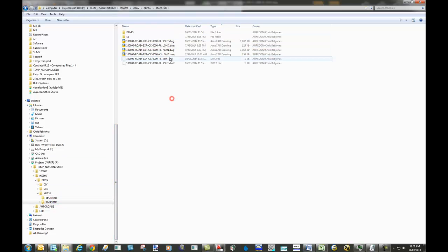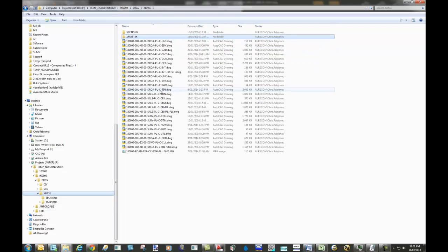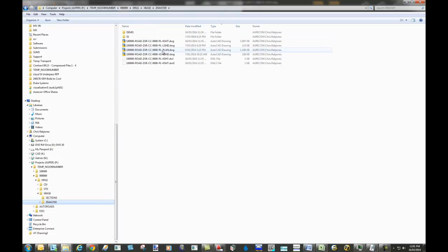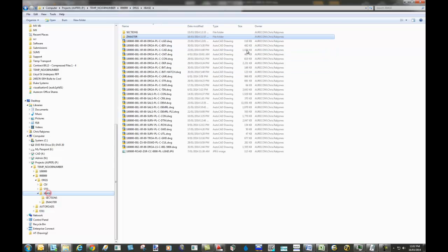In the master file, for every plan type, we only require 3 pieces of information: the key sheet, which contains all the text, UCS views and north points and whatnot, a legend, and a master file that contains all the child XREFs in the exact draw order that one would want to see, and all symbology is controlled through these files. That's it. You never have to turn off or on anything else ever again. You set the colours, the line styles, the widths, everything just once. Okay, let's go.